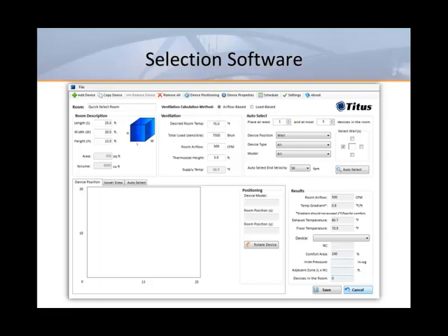We consider the comfort zone to be the floor space outside the adjacent zone of the diffuser or diffusers. While standard default terminal velocity of the adjacent zone is 50 feet per minute in our program, it can be set to whatever value meets your requirements. The program also maps out the adjacent zone and allows the diffusers to be moved around the room.